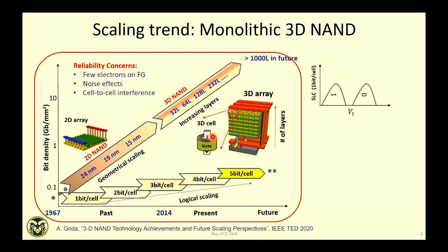Okay, so this is the, yes. Is there any problem with power dissipation with multiple layers on top of each other? Yes, a little bit, but not significantly different power dissipation-wise, because you have a wider plate word line, right? Earlier the word line was a line in 2D, but now in 3D, your word lines are plates. So capacitance will be a little bit larger. So you may increase a little bit of power, but you are also increasing bit density. So per bit, power remains pretty much the same.